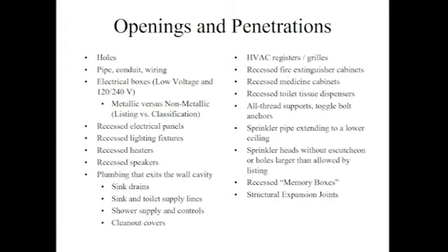And I guess that makes some sense since you're putting a sprinkler head right in front of the hole. But if the hole is larger than the escutcheon, or the escutcheon actually has vents or holes in it, some authorities having jurisdiction, such as DADS, have ruled that holes in the escutcheon mean it's not solid and therefore does not meet the exception, and you have to fire stop it accordingly.